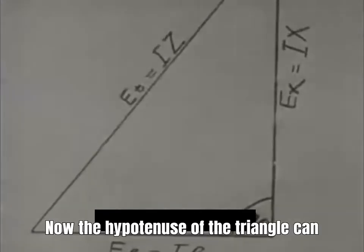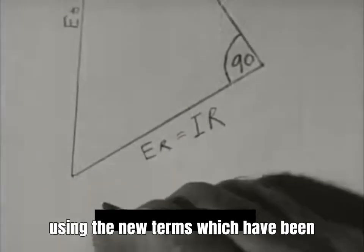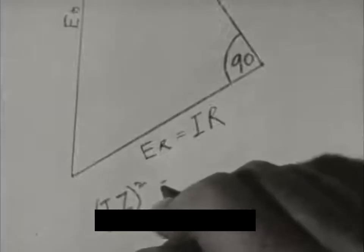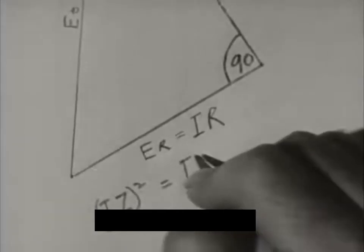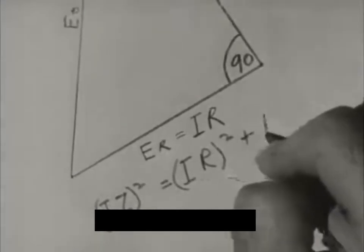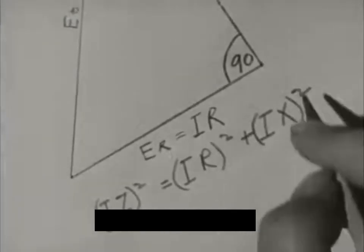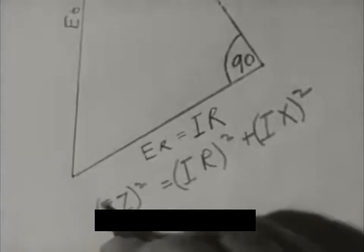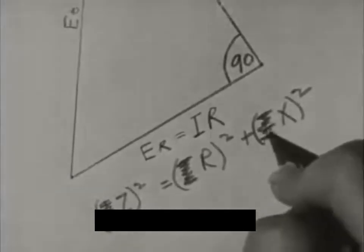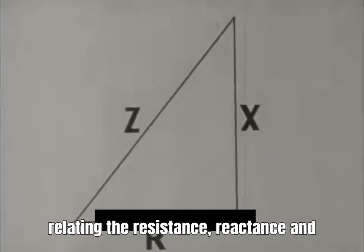Now the hypotenuse of the triangle can be found as it was before, but using the new terms which have been substituted and which contain the circuit values. IZ squared equals IR squared plus IX squared. Then the I's can be taken out. And you have a triangle relating the resistance, reactance, and impedance.